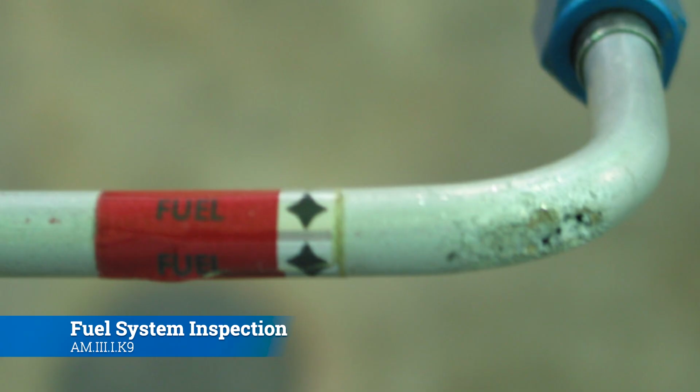Okay, here's an example of a fuel line that exact thing has happened to. You can see that the elbow right there is starting to wear through because it's rubbed up against something and some sort of damage happened. That's going to lead to, for one, low fuel pressure, and number two, you're going to end up having a fuel leak inside of the airplane, and as that fuel leaks inside of the airplane, it could lead to a fire.